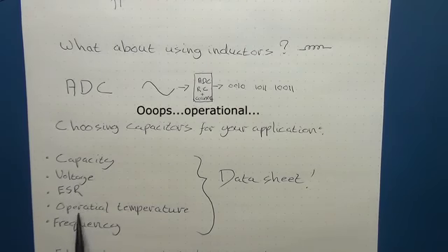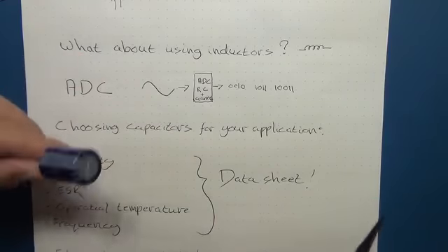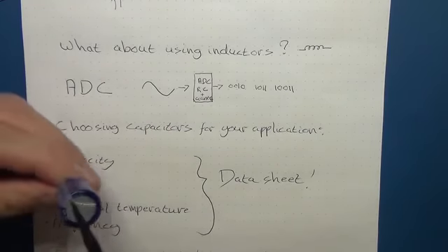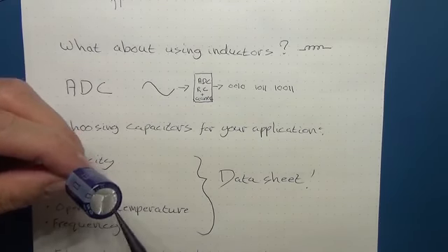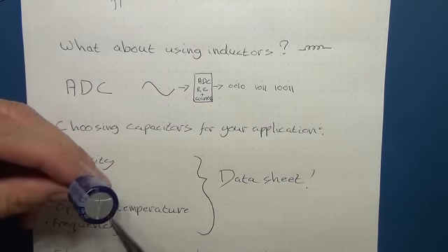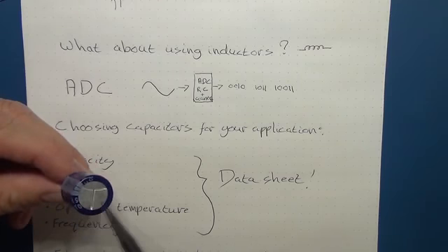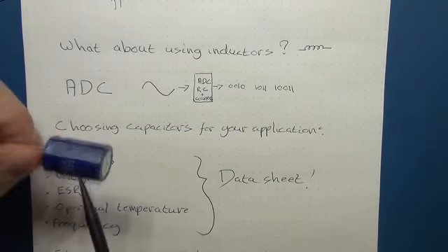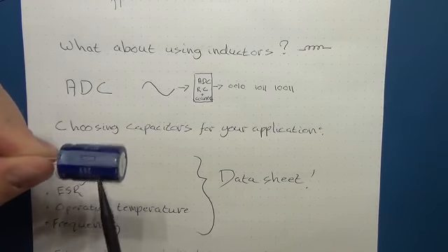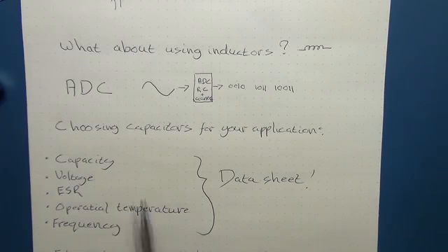You want to see what operational temperature they work at. If you've got it in a power supply and there's hot temperatures, you may have capacitors which are going to fail. And in fact, that is one of the big issues with these electrolytics, because they've got the dielectric, there's potentially fluid inside these, and these can rupture, or the fluid over time can ooze out or dry out, and that's going to change its characteristics, and that's where appliances or electronics potentially stop working.